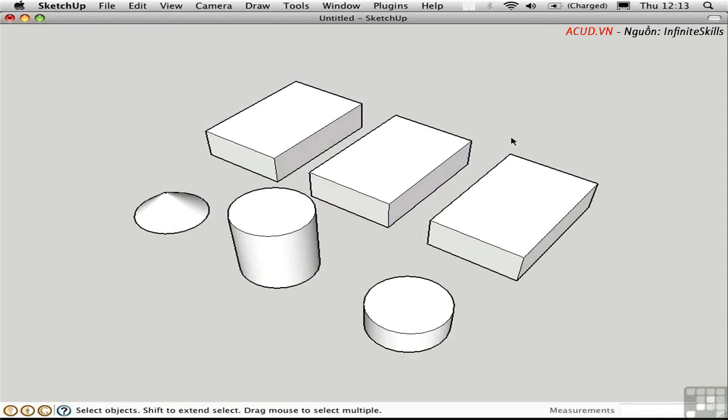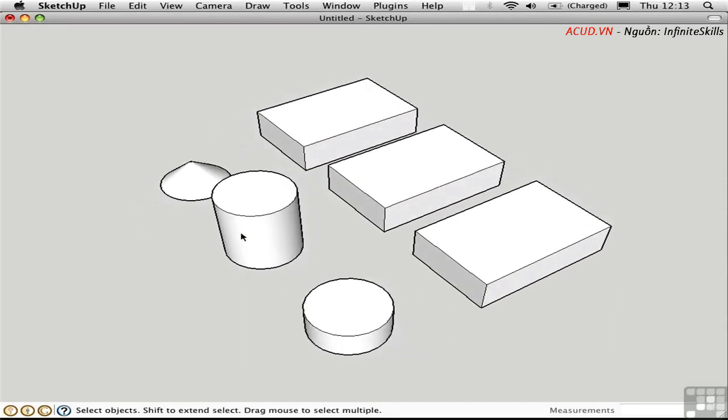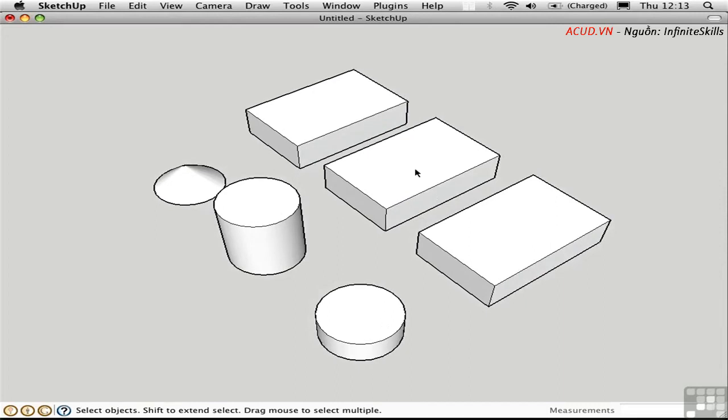It's a common need that we have in 3D applications to have this differentiation between unique objects and objects that share the same geometry. Components are very efficient because SketchUp only has to remember the representation of what's inside the container one time, and then it merely needs to position these instances in different places in space multiple times. So it's essential that when you're creating many duplicates of an object, that you think ahead and create that as a component, and then the file size will be smaller, and you'll have more editing power over the myriad copies.